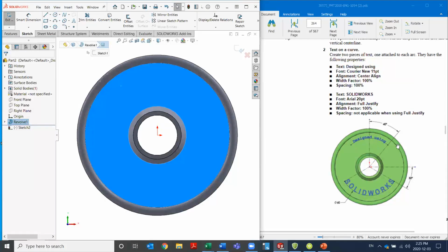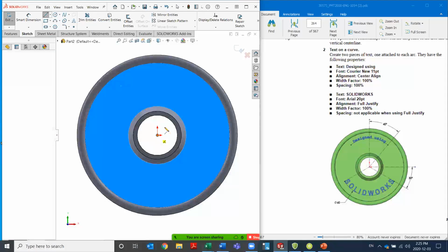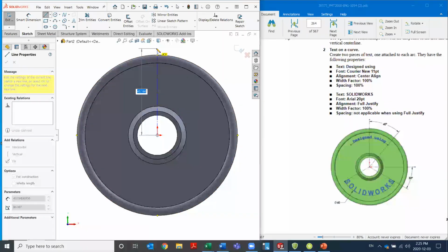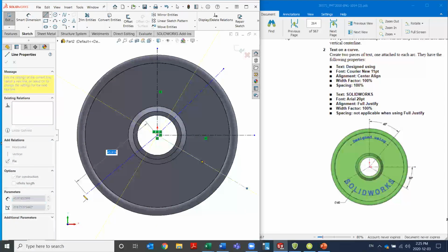And when I see a bunch of construction lines in here, typically that means I'm going to add those in too. And because they're construction, I'm going to add those in first. That's just kind of a best practice there. So I'm going to hit L to get my line tool. I'm going to say for construction, and I'm going to use the click and drag method again here, just to drag these out. The click and drag means I don't have to worry about lines being added on at the other end here. So I can quickly just drag out a number of lines. What do they have? One more, it looks like, down here.